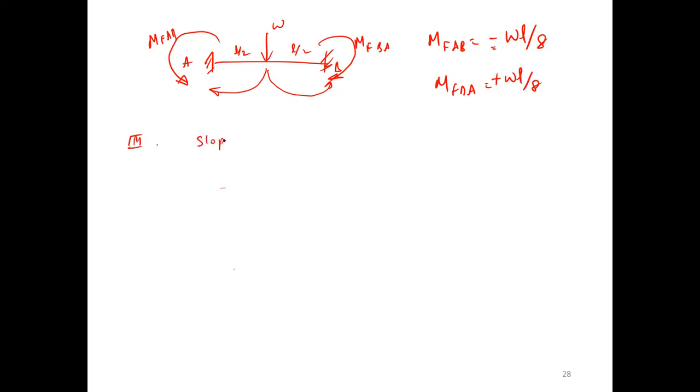Slope deflection equation. My first question is, for this kind of frame, how many slope deflection equations? You know, the kinematic indeterminacy of this frame is 3.